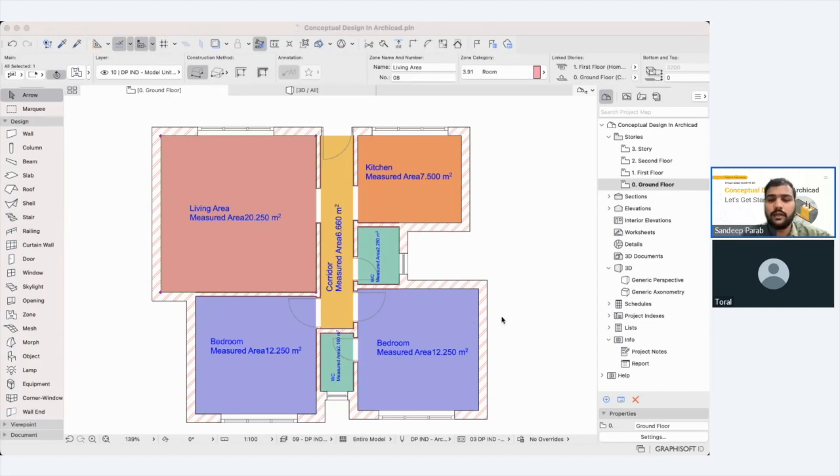So I have just duplicated the glass and I have just given the color for it. So if I can show you in the settings of surface. So yes, these are the zone surfaces that I have created. And here you can see, I have duplicated the clear glass surface and I have just given the surface color over here. So whatever RGB or color from the spectrum you select, that color will get applied to this. Okay. So you just have to duplicate and give the surface color for it.